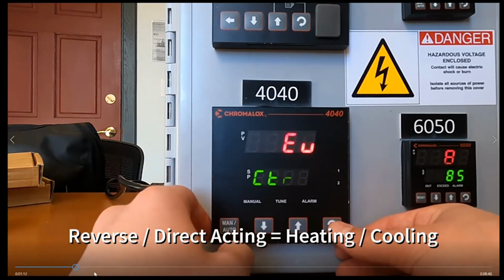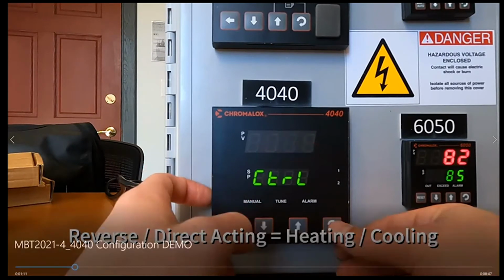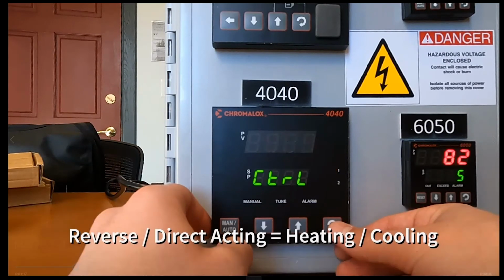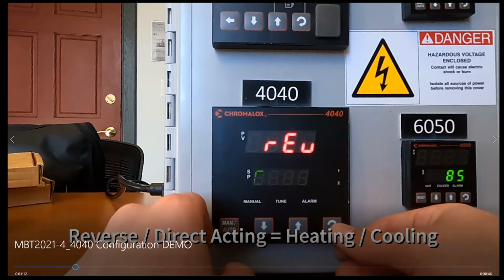Derek briefly talked about reverse versus direct acting. I like to think of direct acting being more like an air conditioner in your home. After the set point is hit, direct acting means you're going to turn on whatever process you have running once that set point is hit. We're in the heating world, we're a little bit backwards, where we want our heater to be on and heating up a process until that set point is hit. So that's why all of our controllers come standard reverse acting, because you want the heater to turn off once the set point is hit, not the opposite.